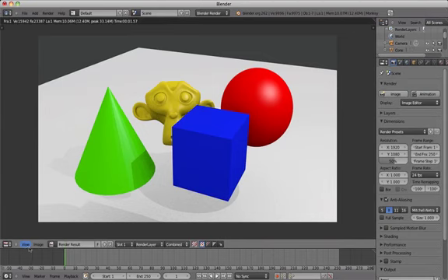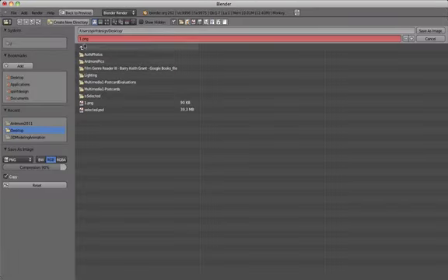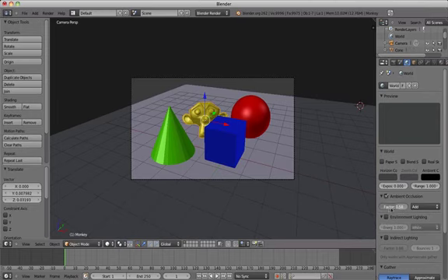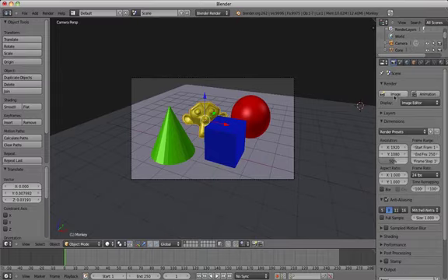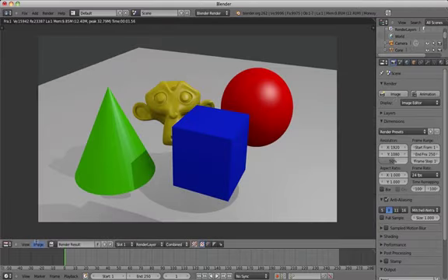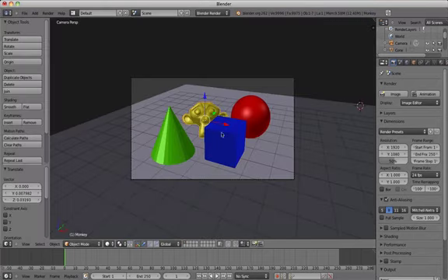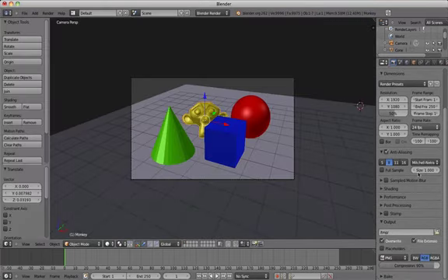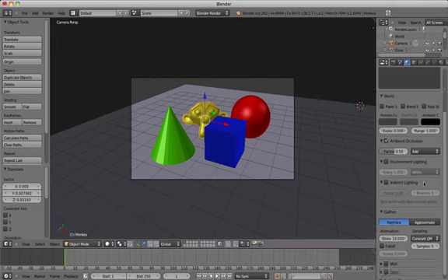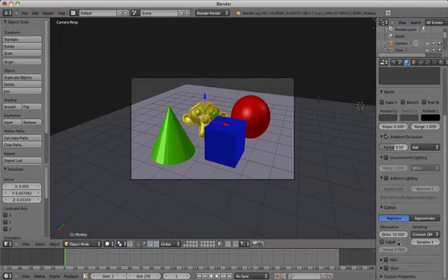You can change some of the settings of the ambient occlusion. For example, you can adjust the factor to 0.5 and re-render to see the difference. When ambient occlusion is on, the gather options become available. Change the samples from 5 to 15 to make the graininess go away.